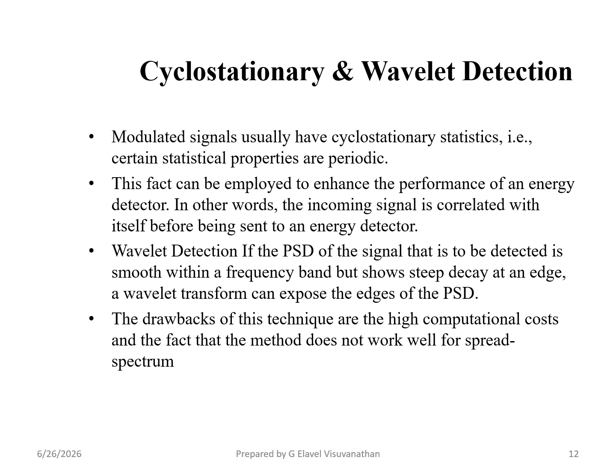Wavelet detection: if the power spectral density of the signal to be detected is smooth within a frequency band but shows a deep decay at an edge, a wavelet transform can expose the edge of the power spectral density.